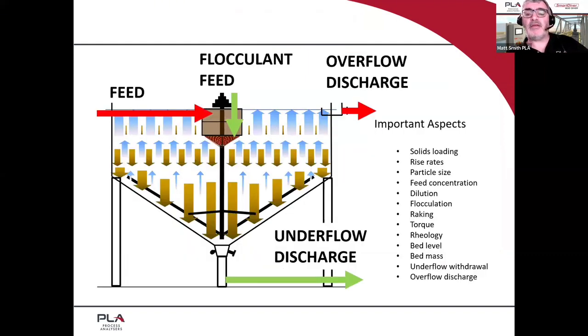And we can see that for any thickener, there are a lot of processes going on inside the thickener, with only the two levers to help control the thickener: flocculant addition and underflow extraction rate. And this is where I introduce John Karageorgos, who will discuss these important aspects. Over to you, John.